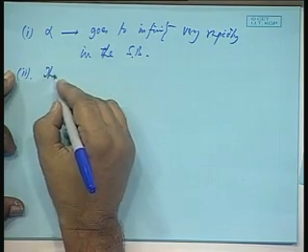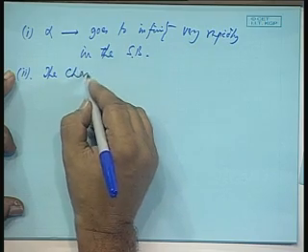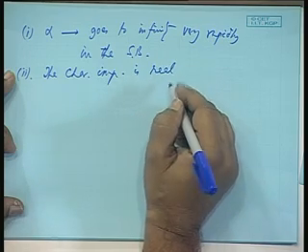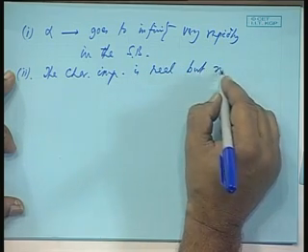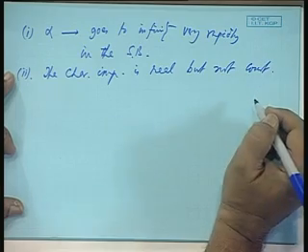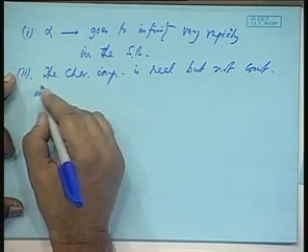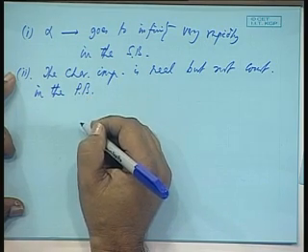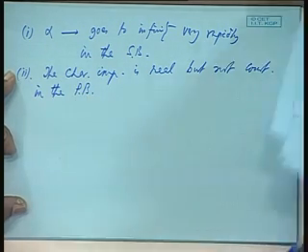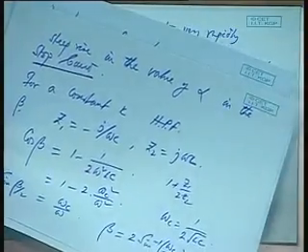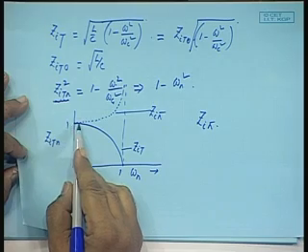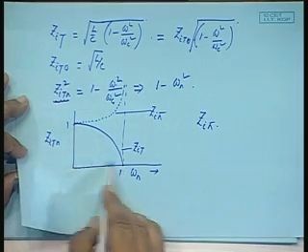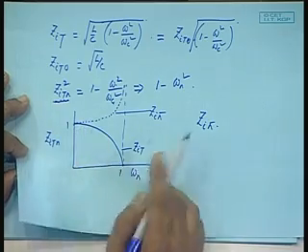The characteristic impedance is real but not constant in the pass band. It varies, as we have seen earlier. The characteristic impedance was gradually changing, the normalized value was changing from 1 to 0. So, in the pass band the characteristic impedance does not remain constant.